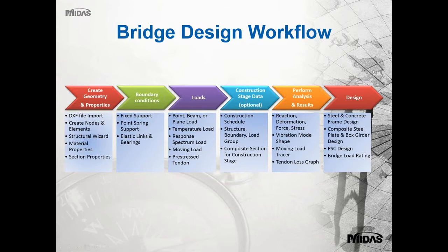The design workflow for any kind of bridge that we follow in the software Midas involves creating geometry first of all and assigning it its properties. Geometry can be either created within the software or you can bring it from AutoCAD files, basically the DXF file format.